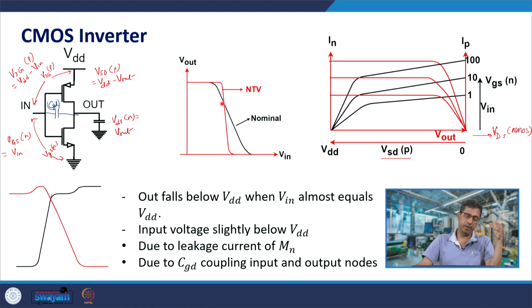For a given value of input voltage, the output would settle to a certain value, and the output capacitance would no longer be either charged or discharged. Suppose you keep the input voltage at a certain value and the output voltage is larger than what it is supposed to be. Then there would be a net current in the N MOSFET, larger than the current in the P MOSFET.